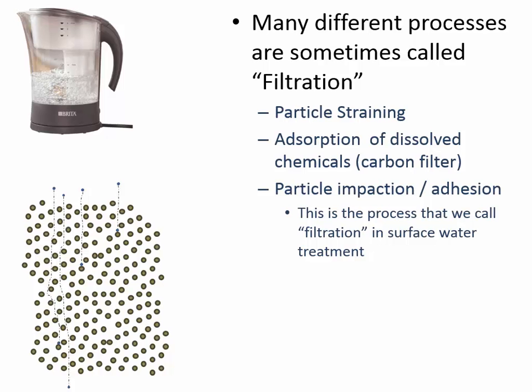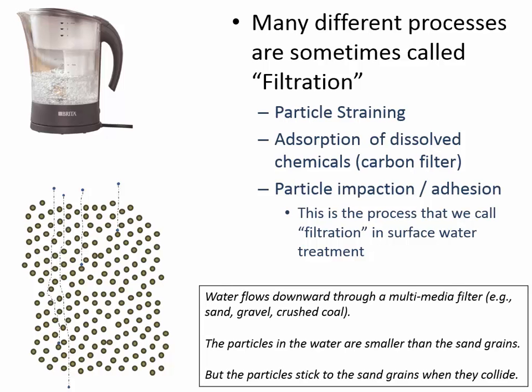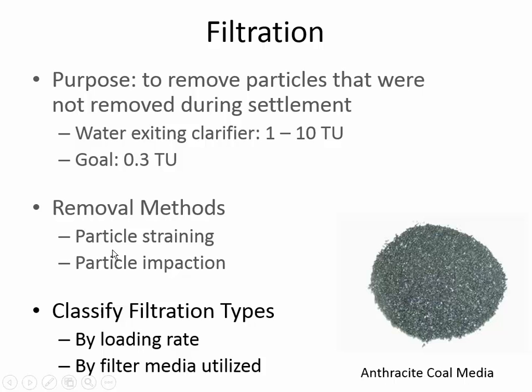So some of the particles are going to get through, but the majority of them are going to hopefully be removed so that we can make sure the water is pure. The review here is the water is flowing downward through a multimedia filter. And multimedia means it's not actually only sand that's inside of this filter. We'll have crushed gravel at the bottom, and at the top sometimes they'll add a layer of crushed anthracite coal, just to try and make it so that the void sizes are smaller, so that there's a range of particle sizes. But these particles will stick to it, even though they're not strained.